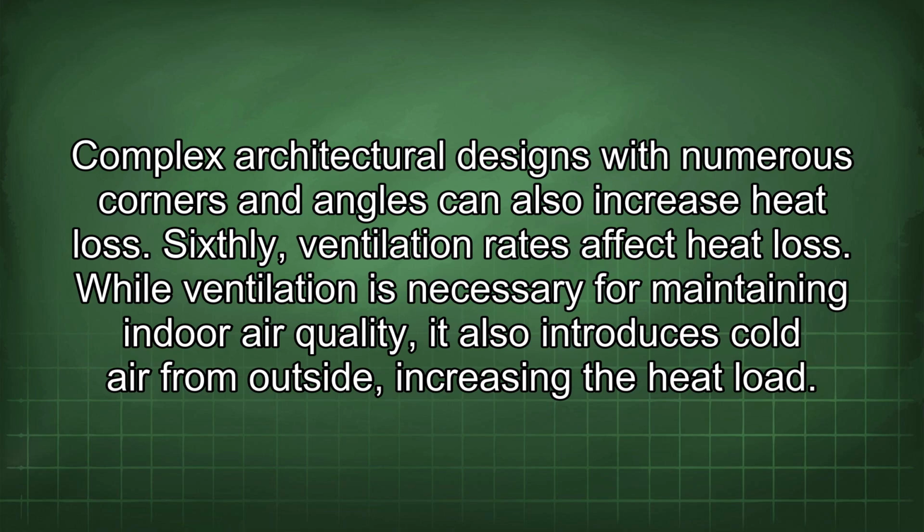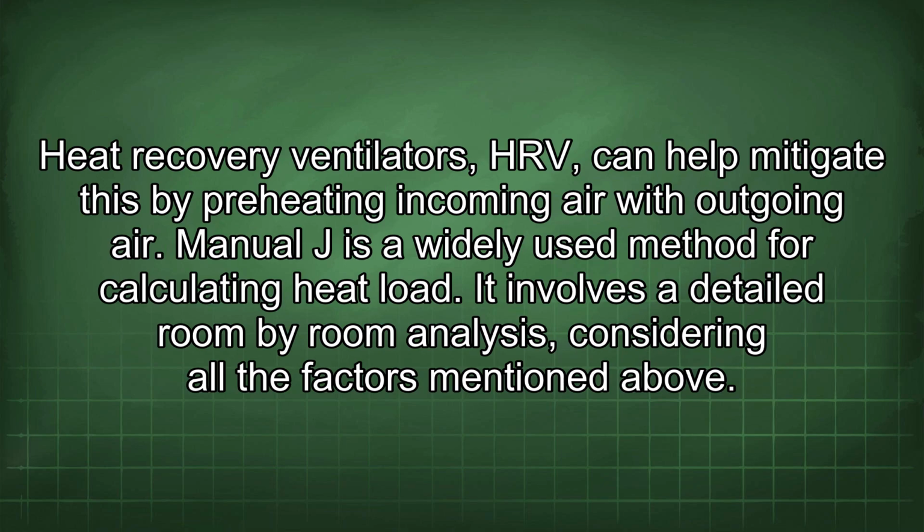Sixthly, ventilation rates affect heat loss. While ventilation is necessary for maintaining indoor air quality, it also introduces cold air from outside, increasing the heat load. Heat recovery ventilators, HRV, can help mitigate this by preheating incoming air with outgoing air.